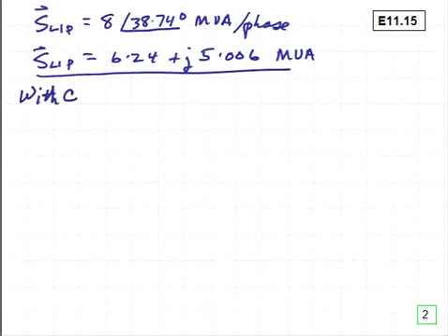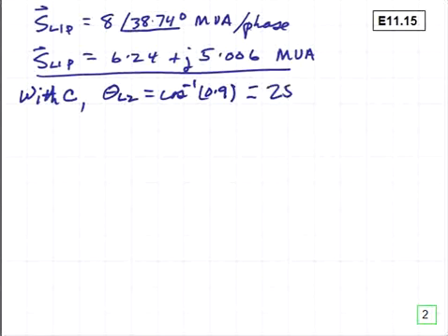With the capacitors inserted in the system, we'll have that the theta L2 angle is equal to the inverse cosine of the new power factor 0.9, which is equal to 25.84 degrees.